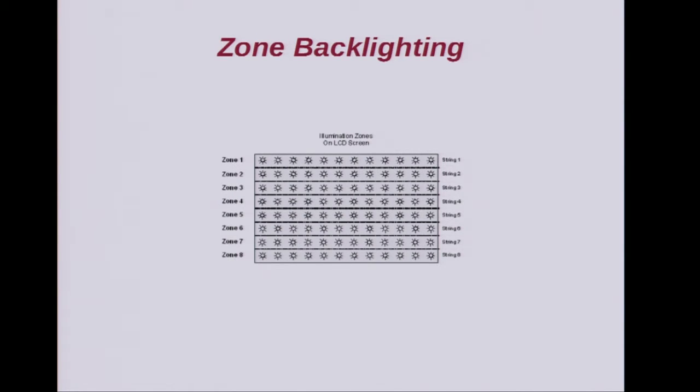And one of the things we did for various companies, they wanted to be able to control the backlight of an LCD. So instead of just having a strip, although that works as well, 10 years ago, 8 years ago, people were getting into changing the brightness of the backlight by zones, because an LCD only has a limited contrast ratio, and the marketing thing was who can beat who with the contrast ratio. 1,000 to 1 didn't sound very good, so the marketing guy wants 1,000,000 to 1. So how can you get 1,000,000 to 1 if the liquid crystal display's only got 1,000 to 1, and that's pushing it? To get more of a contrast ratio, what you can do is look for the dark areas on the LCD and dim them down.